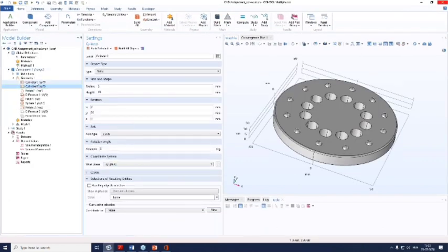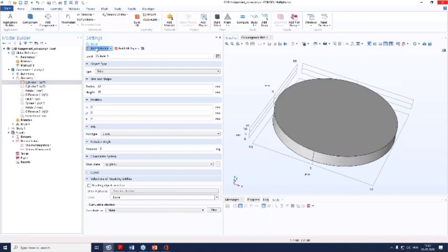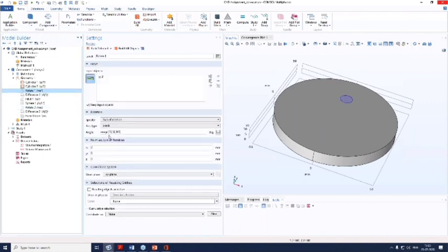First you have drawn one basic cylinder, and on top of that, if you have drawn the next cylinder, we have directly used this rotate feature only. That is, at 30 degrees difference up to 360 degrees, the circular array has been created. That is how you can create your entire circular array. Writing down or calculating coordinates for each and every object is going to be really very tedious, and that's why this kind of rotate feature can be used efficiently.